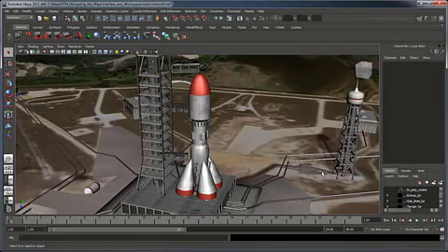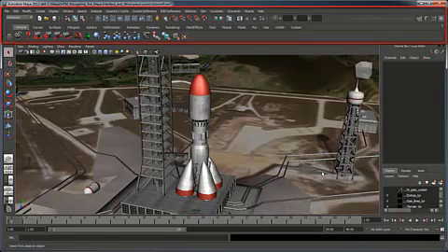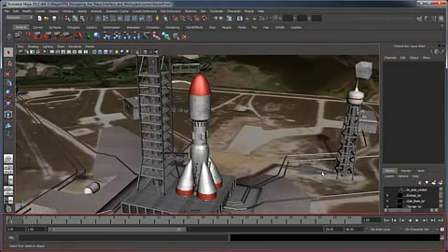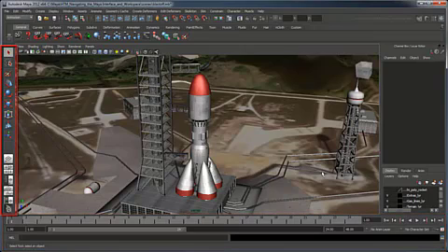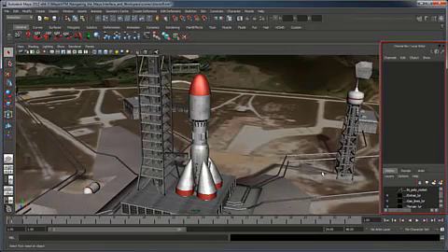The Maya interface is divided into 4 major regions. The upper region contains the menus, status line, and shelves. These tools are mostly used for creating and editing objects in your scene. The lower region contains the time slider and command line. These tools are dedicated to animation and scripting. The side regions contain the Toolbox, quick layout buttons, channel box, and layer editor. These tools allow you to manipulate objects in your workspace or the layout of the workspace itself.